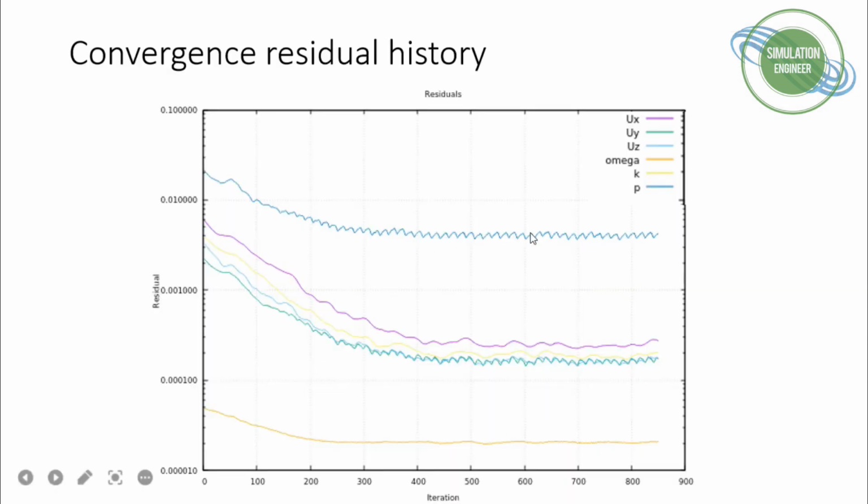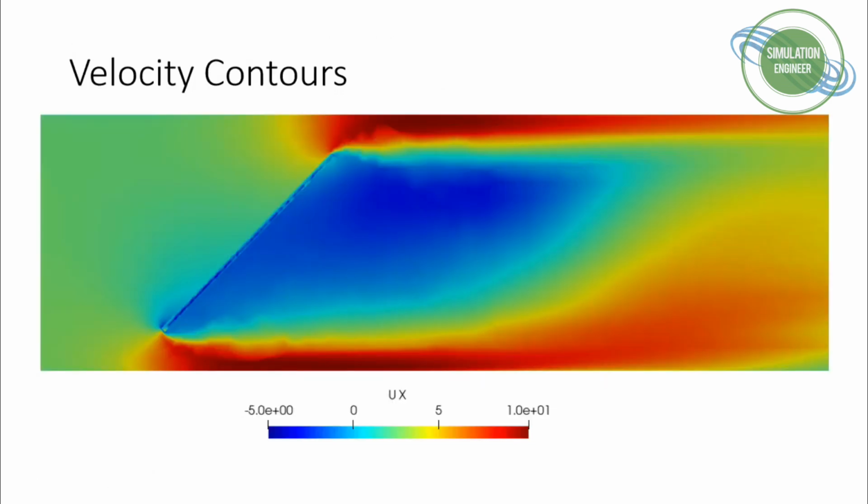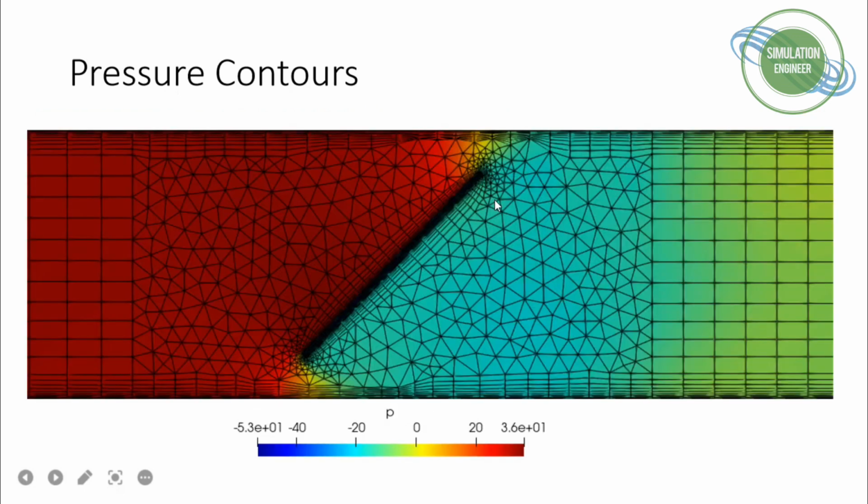Okay. So if we now conclude our video session, we can say that very nice convergence has been achieved. And we can also see once again this one snapshot of a velocity contour. There it can be seen that accelerated flow is coming in these regions, just these small channels which are not covered by the damper. So the incoming velocity is coming from this side, and you have a flow acceleration, and then just completely behind this damper there is a large flow separation.